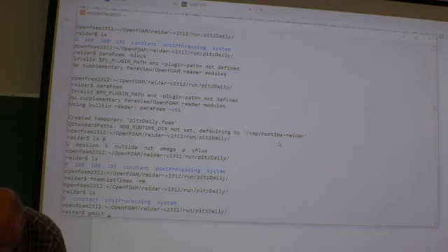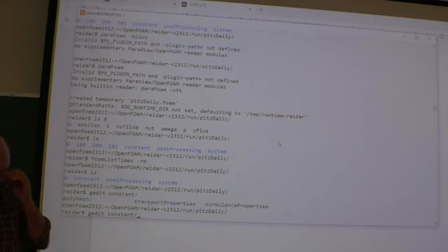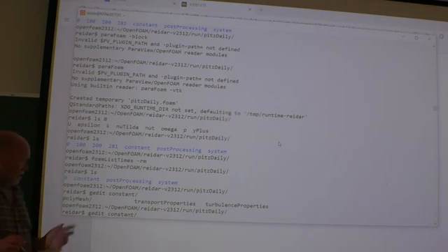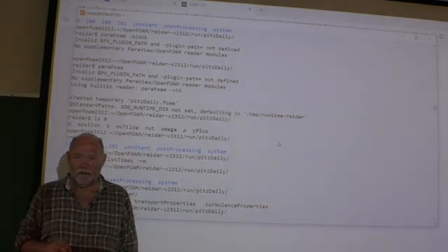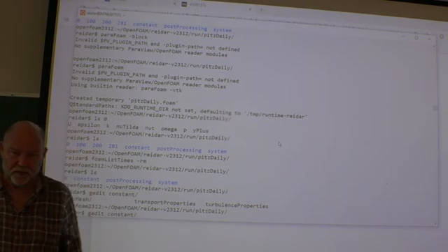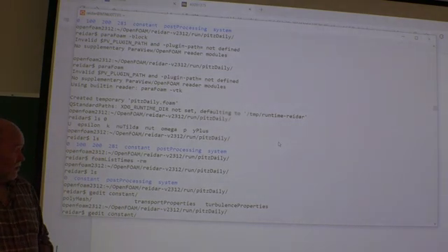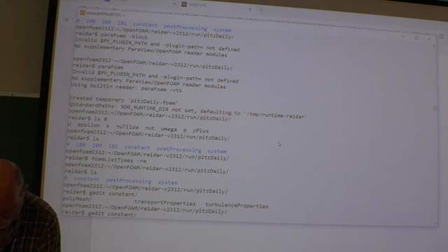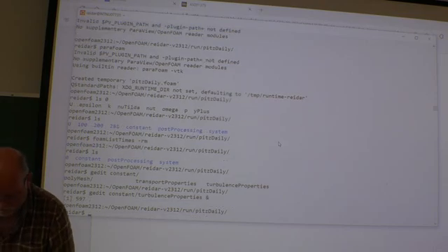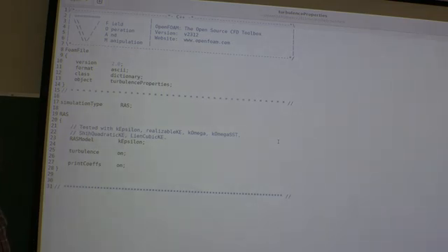So let's start with looking at the file in the constant folder that has something to do with turbulence. In my version, it's called turbulenceProperties. I wonder if normally you guys have something in momentum something. Anyhow, you should be able to find it. It's not that many files here anyway. So let's have a look at this file. And here looks something like this.